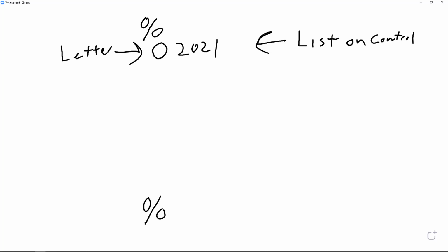Okay? Very important. Now, usually after that, you're going to have something in parentheses, and parentheses mean that it is just a comment. The machine doesn't necessarily read it, it's just for your reference. So in parentheses, we can put whatever we want. There is a numerical limit, okay? So just beware of that. It can't be a paragraph, but this could be "example." Okay? Then after that, we get into tool information, work offset information, things like that.